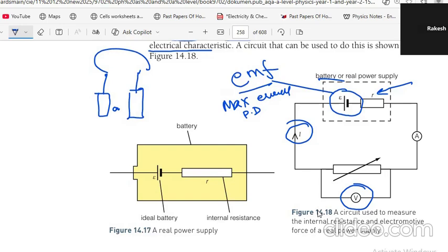But when it starts flowing, the battery itself has some ions here, right? So they are pushing the electrons. But once they start pushing, there will be some chemical transfer, ion movement here. Now this requires some energy. So at that moment, it uses some energy for itself. That is the internal resistance. Supposing this can give 12 volts, but it itself is using 1 volt. So it is effectively giving 11 volts outside. That's the voltage you measured.